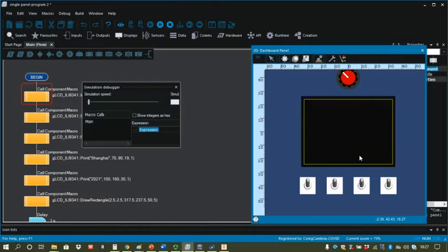Either active or inactive is the message, depending on where they are. The way I've done this is we have a set point and a calibrate point, and once it reaches that calibrate point, which we can do on these 4 buttons here, we can set it so that as the stabilizers come down, there is a point where they change from inactive to active, and when they go back up. And I've done that with a very simple count. So every time the button is pressed, it goes through.